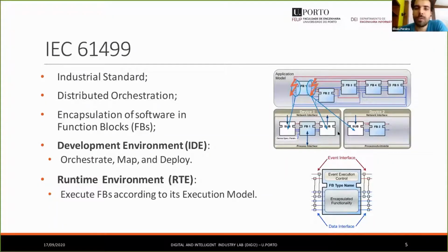So the user orchestrates a pipeline of function blocks which can perform a certain operation, like moving a robotic arm and so on. Then the user maps each function block to one device that is running a runtime environment, and the IDE automatically sends the function block to that runtime environment to execute it.